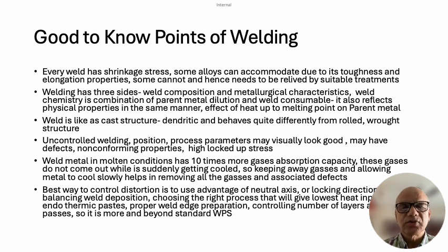And if there are service conditions which are going to have cyclicity at higher temperatures, higher pressures or higher loads, this entrapped hydrogen gas in these porosities or inclusions, which has already created a small notch because of its high pressure, starts propagating that notch into a crack, and a phenomenon called cold cracking or delayed cracking takes place.